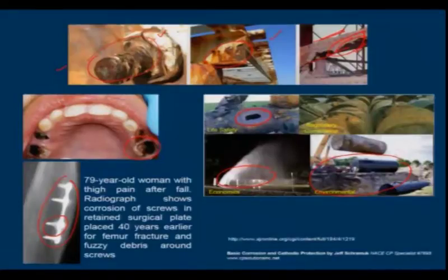Now, poorer grade means with reference to the corrosion resistance of those metals. In that case a kind of corrosion happens which is called galvanic corrosion, and there the connector which actually takes water pipeline to the pipeline inside the bathroom, that gets corroded and leakage happens. So, this kind of stuff many times happens in our day-to-day life.